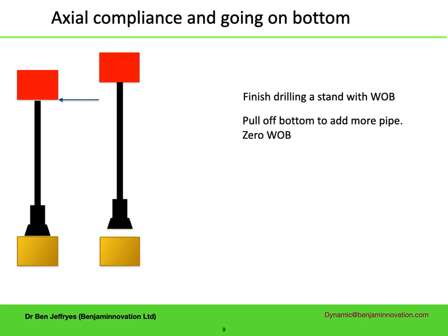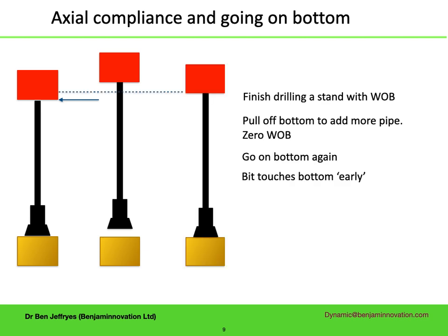Up comes the block, and the bit comes off bottom, but now with 0 weight on bit, so the drill string is longer. The bit doesn't come off bottom until weight hits 0. Back on bottom, and the block doesn't have to go down as far as it went up to touch bottom. Like with objects in your rearview mirror, the whole bottom may be closer than it appears.